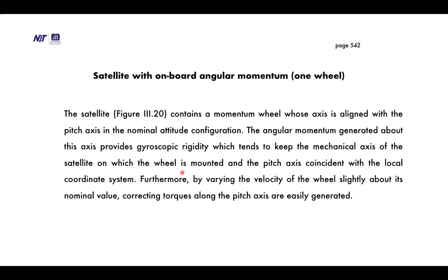Attitude control in normal mode is as follows. Pitch and roll angles are measured by one or more earth sensors operating in the infrared region. Gyroscopic stiffness conveyed by the momentum wheel enables movement about the roll and yaw angles to be limited.